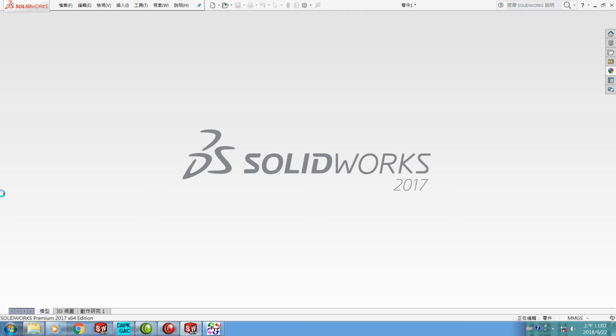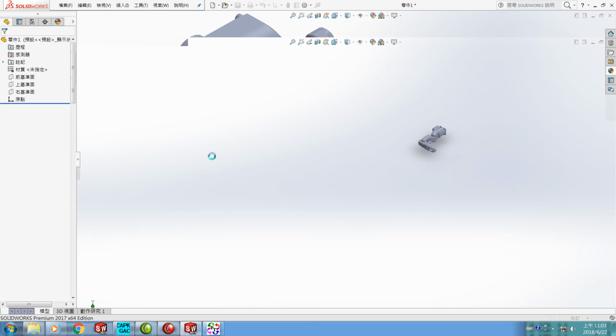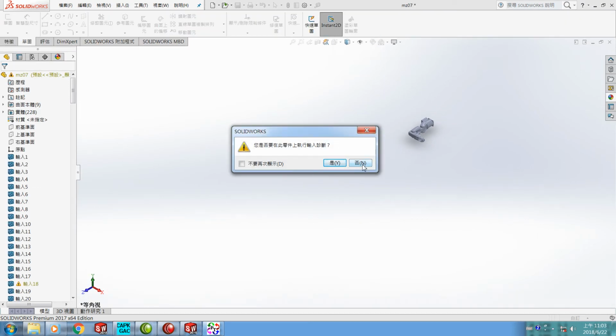The 7 components, including the tool, has to be translated from IGS file into X file. Then we copy all the X file into CMS CAPP data file folder and filling into Excel CSV file. That's the procedure we have to do.